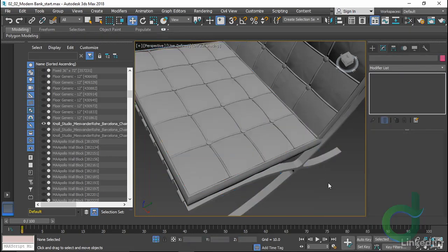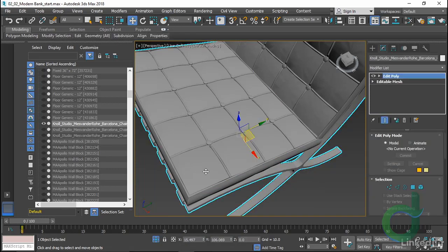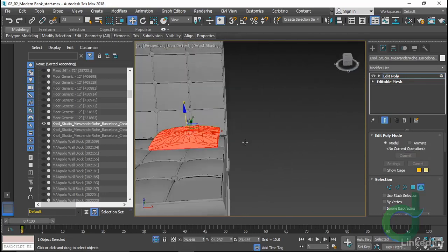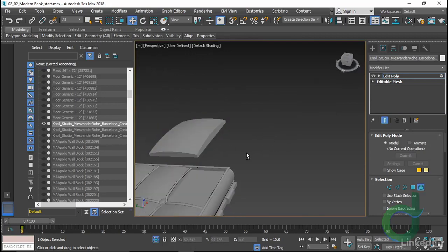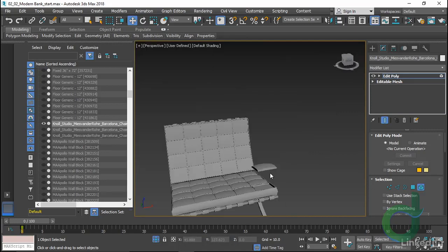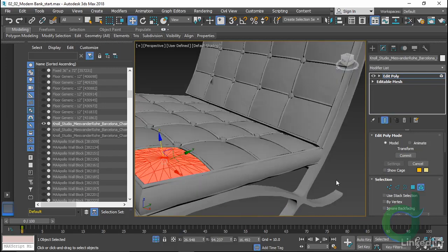This looks much better. Now what we're seeing is that this smoothing, because it's set to 30 degrees, is not catching the sides of those leather pieces. Instead, and I'll press 6 or 5 to go to element, pick one, pull it up, we can see that the straight sides of this tuft are staying straight. The top, this rounded section, is smoothing over, and the bottom is not smoothing at all. I'll undo to push that back in, and then work over the back in the same manner.